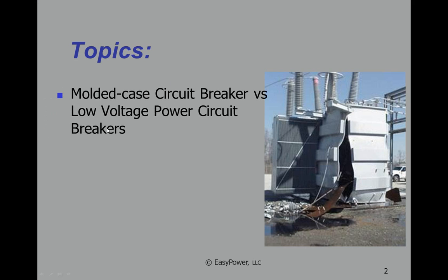So we're going to talk about a few random topics. First one is molded case circuit breakers versus low voltage power circuit breakers. That question comes up a lot, as far as why you would use one over the other and what the advantages are. We're going to focus mainly on coordination issues, but also we'll talk a little bit about short circuit duties. We'll talk about coordination of molded case circuit breakers, or the lack of coordination at times. That's become a bigger issue now because of some of the new requirements in the National Electrical Code.